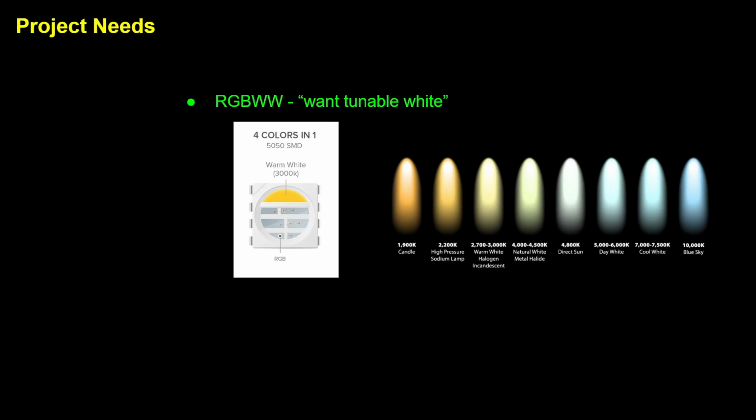The lower the Kelvin number, the warmer the light. Just for reference, a normal incandescent light bulb is generally around 3000 Kelvin. While the white light produced by just combining the RGB LEDs to try to produce white is up somewhere around 7,000 to 8,000 Kelvin. So when using an LED bulb or strip with dedicated white, you need to verify the actual number and types of white LEDs used,